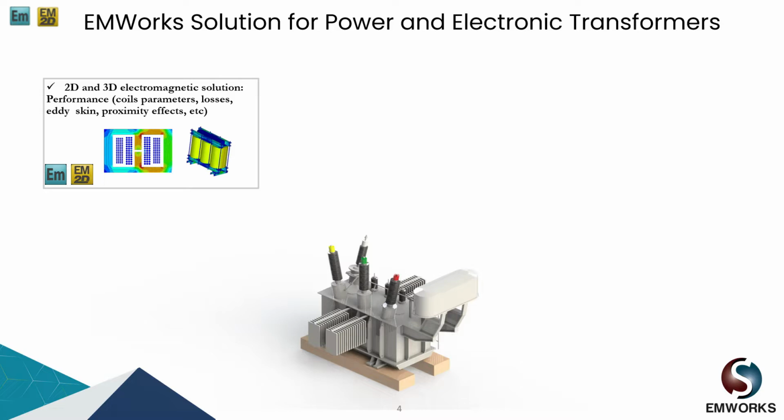So 2D problems are used at the beginning and at the middle stage of the design process, because 2D analysis runs faster and we can solve more iterations in less time, while the 3D analysis is usually used at the end stage of the design process to validate the final results, because 3D simulation can take into account most of the 3D related physical phenomena.